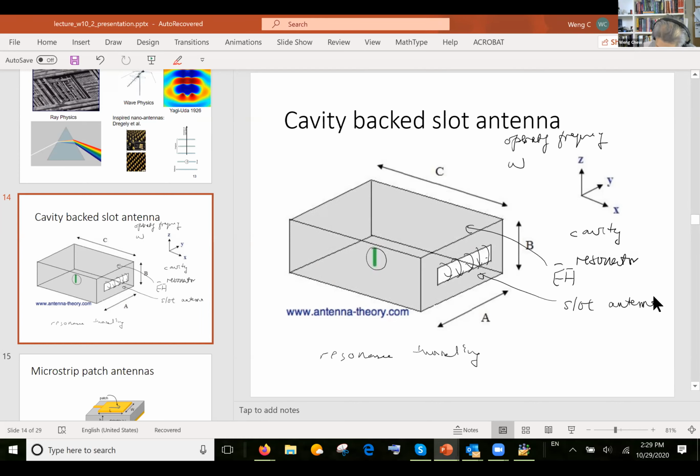So it is very much the same principle as an LC tank circuit: in order to get the current to be large, you have to hit the resonance frequency of this LC tank circuit, then you get a huge current to flow through it.